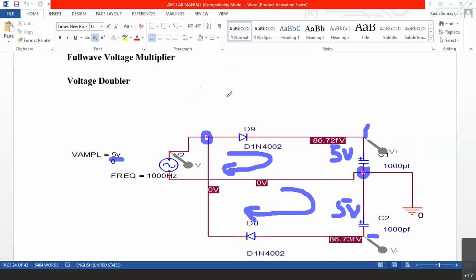I don't think there are any questions here. Do you have any questions? And you can see the diode which we use is 1N4002. 1N is normally the notation for diodes. Americans use this convention. 2N is the notation for transistors with the American convention. And 4001, 4002, 4003, that way it goes on up to 4007, there are numbers. Now that 4007 diode can withstand 1000 volts PIV, peak inverse voltage. In the reverse bias, it can withstand 1000 volts.